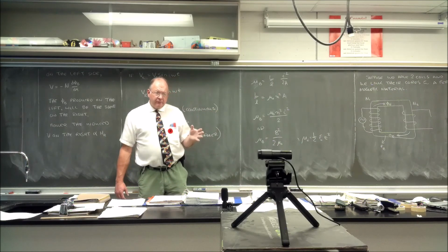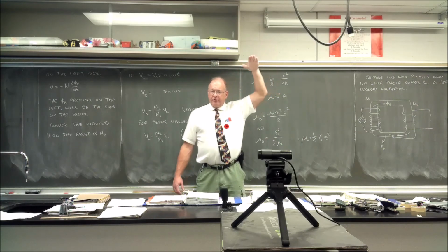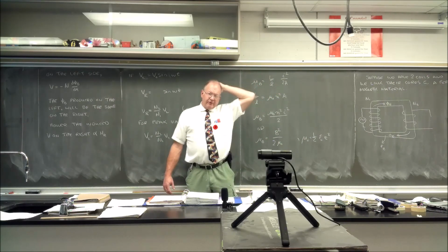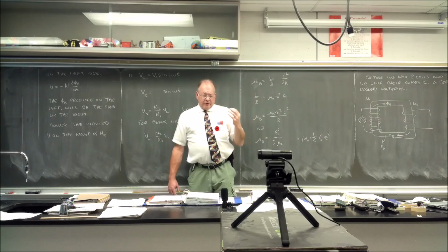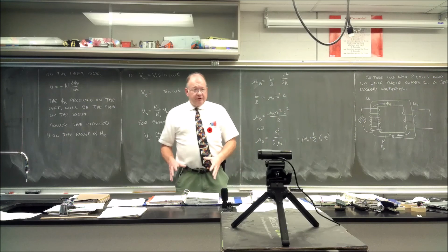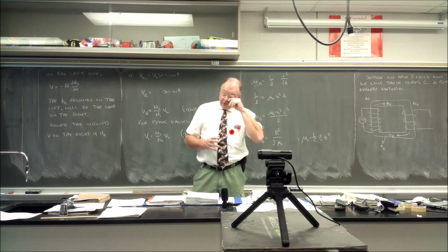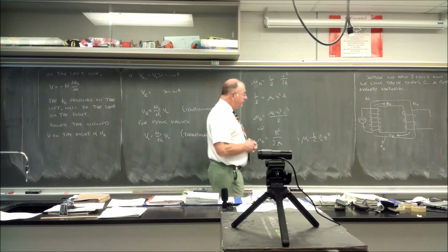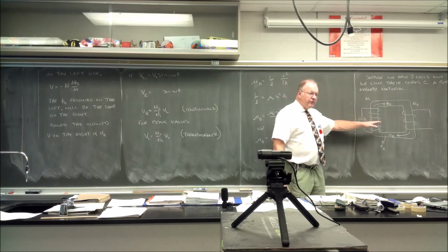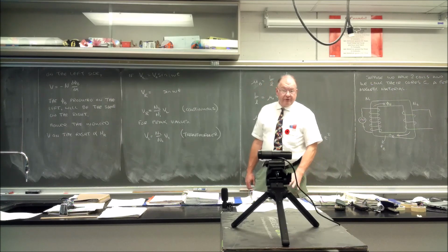One is we have big long lines, so you want to get the voltage as high as you can, so you reduce the current, because we know that the power dissipation is I squared R. Okay? So the idea would be power generation somewhere, raise the voltage to high, thousands of volts, maybe more, transmit it as far as you need to, and then step it back down to safe levels so it can be used by the consumer. And this was what Tesla had in mind, and it's what we still do today.